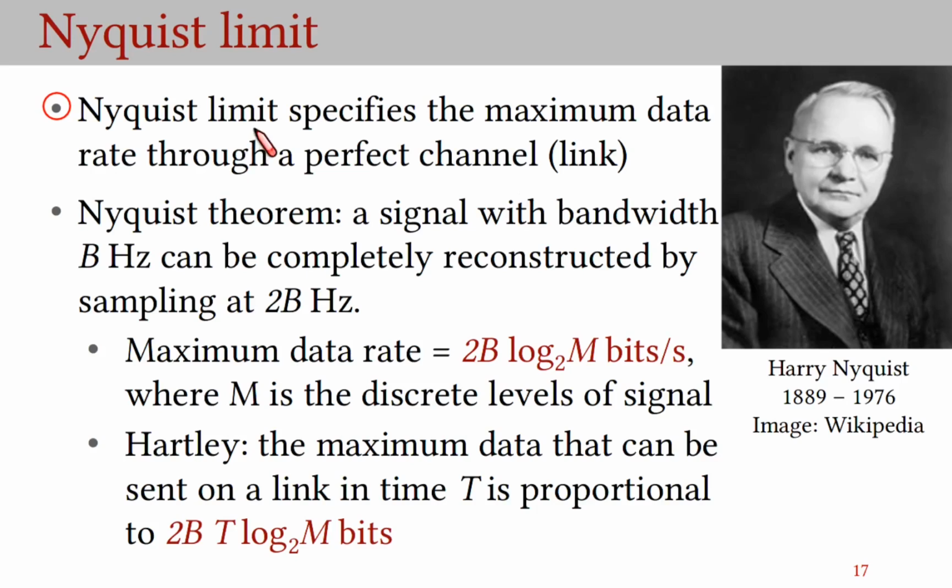This limit is due to Harry Nyquist, who was an engineer at Bell Labs in the US. In 1928, Nyquist established this fundamental theorem that says that a signal with bandwidth B Hertz can be completely reconstructed by sampling at 2B Hertz. A consequence of this theorem is that if a signal is passed through a channel of bandwidth B, the frequency components higher than 2B get filtered out.